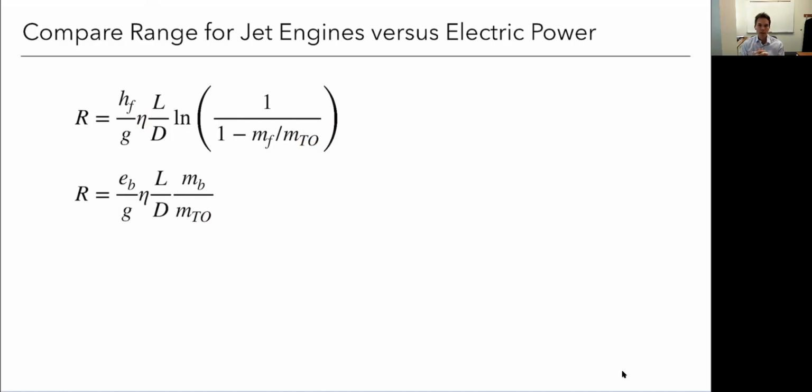So the airplane is becoming lighter and lighter, and it's becoming more efficient because we're not carrying that fuel with us the whole time. So this term can actually be larger than this term for electric aircraft. I have a plot of that in the text if you're interested, on some different assumptions. But both of these are relatively small. This one is for jet engines a bit worse, but this one's a bit better. And of course, the aerodynamics, there are secondary effects, but we can do about as well in either case. The big difference by far is this term here, energy densities.